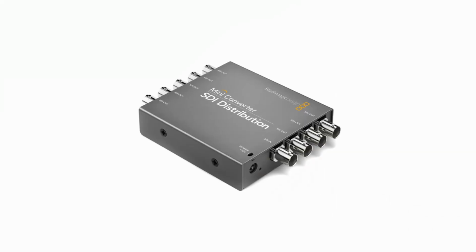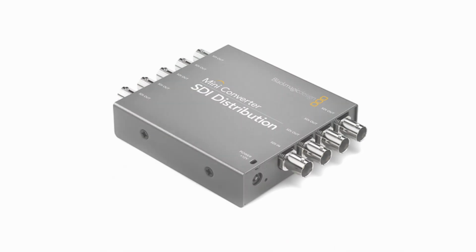So if you have multiple outputs, say you want this video to be shown in multiple rooms, what you need to do is get a splitter. I highly recommend that when you do this, you run everything on SDI cables, because those cables can run for 300 feet before you ever have to repeat a signal. And unless you have a gigantic church, 100 feet to 300 feet should get you almost anywhere you need to go. So what I would do is get an SDI distribution splitter. It's just like any other splitter that you would see, but it just handles SDI coming in and it splits it to multiple places. So I'd run one program out from our switcher to the splitter, and then that splitter would run to the projector, to the other TVs inside of the church, and you can even run it into your other computers if you need be.